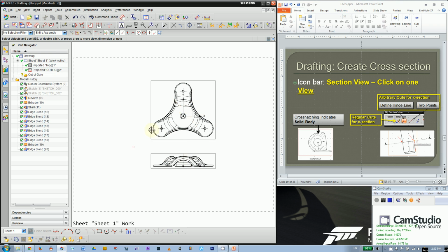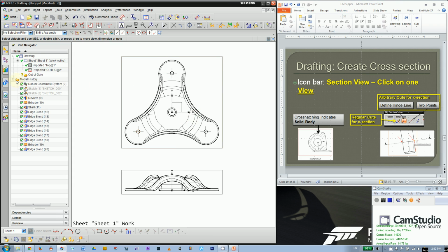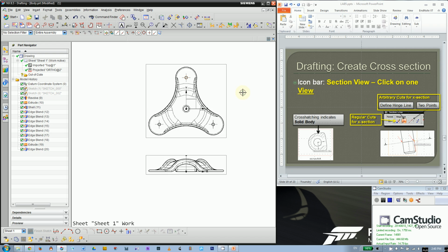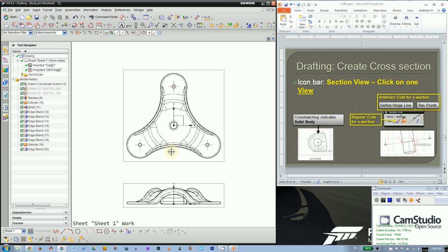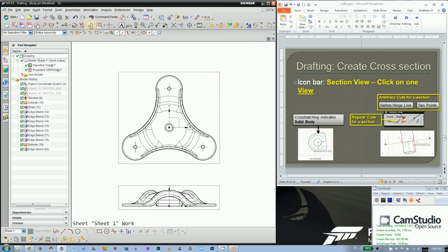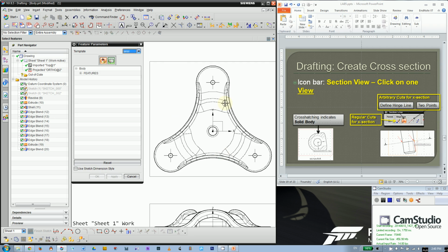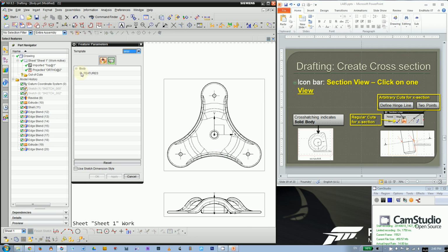Projected from the side. Okay, and notice it's not a template, so there's nothing here. And for this view, right, we have a sketch, and this is a part drafting instead of an assembly drafting. So you want really detailed dimensions, and sometimes even, in reality, the tolerance, you have to have them for manufacturing. Anyway, so this command, the feature parameters, since you already have dimensions for this in the sketch for this part, you don't have to add so many dimensions to this part. You can find your sketch. I think that's the second sketch in this case. Probably the first. Let's try it.